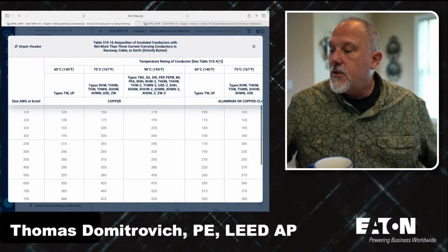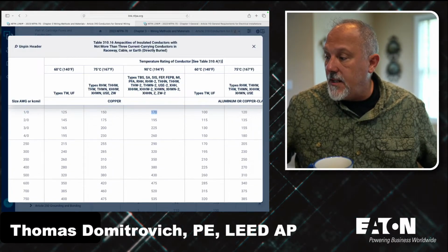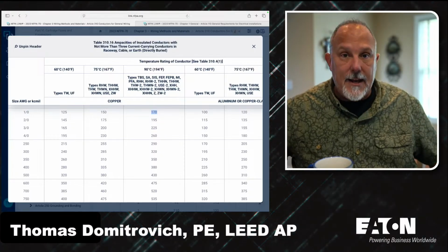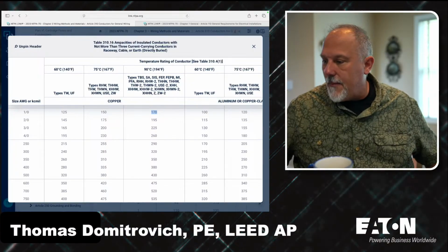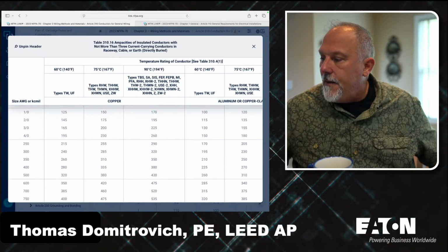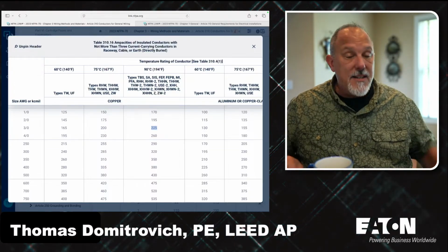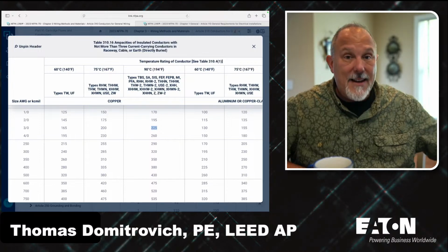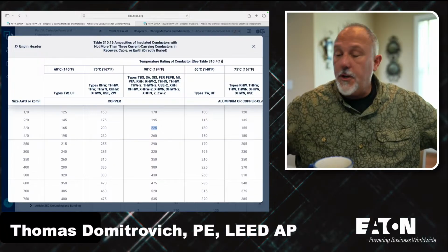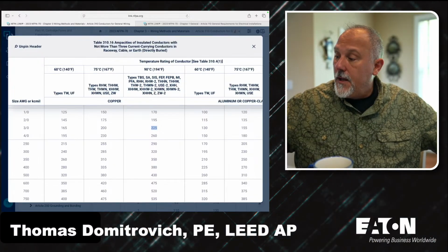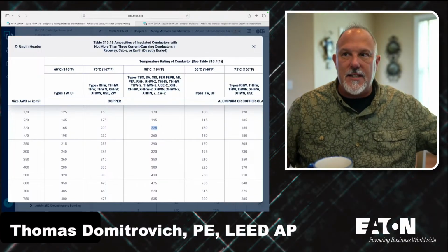So when I scroll down here, you've got to get NFPA LiNK and exercise this stuff. I'm telling you. So let's say that I have a 1-aught conductor and its ampacity based upon these conditions of use is 170 amps. And I say, you know what, I need to increase this because of voltage drop, and I put a 3-aught in. The ampacity of that conductor is 225. Does that exceed what's in the 75 degree C column? Yes, it does. You can't tell me I can't put a larger conductor.